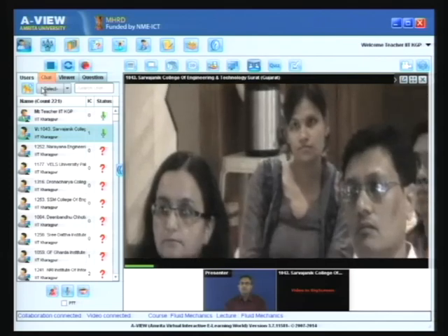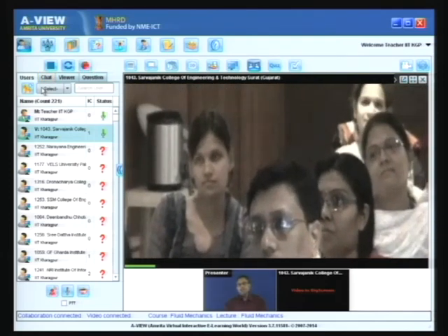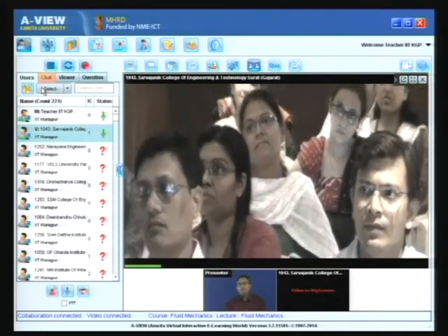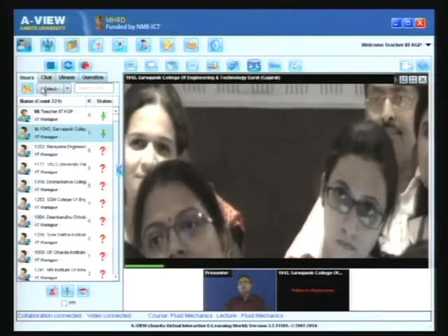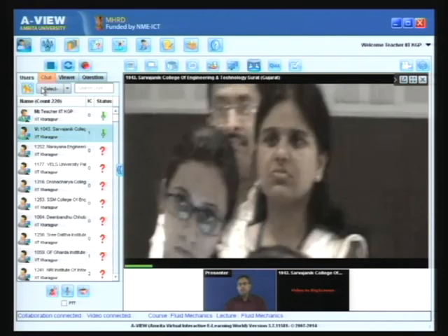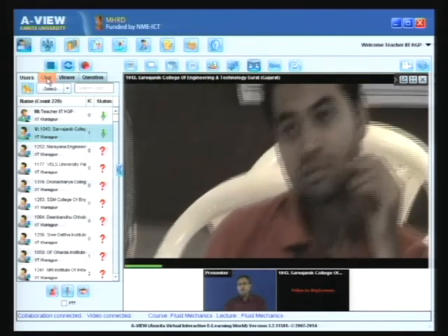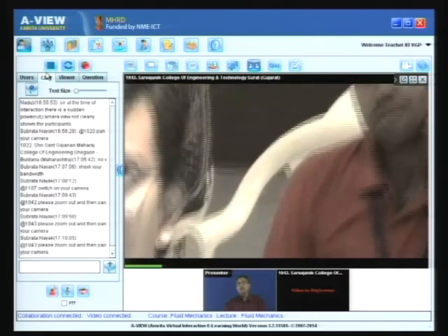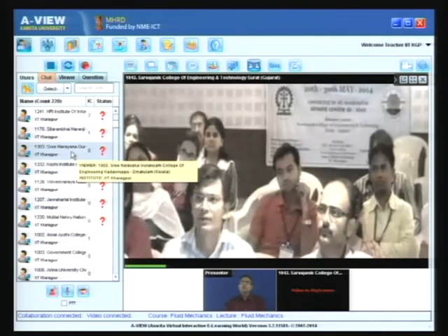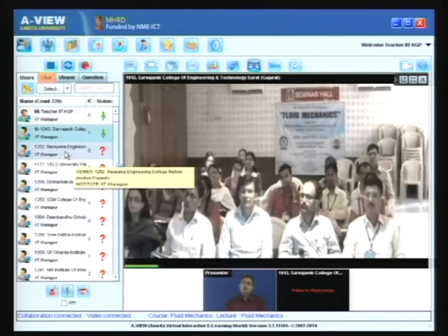We will discuss turbulent flow tomorrow, and there we will discuss the distinction between this kind of flow that we discussed today and the turbulent flow. But just to be precise, there is regular orderly motion of fluid elements, and that means the roughness effect does not perturb the flow. The effect of roughness or wall undulations, I mean local fluctuations in the wall profile, after aging or before aging, does not come into the picture when you are considering a fully developed laminar flow. So, friction factor is a function of Reynolds number only.